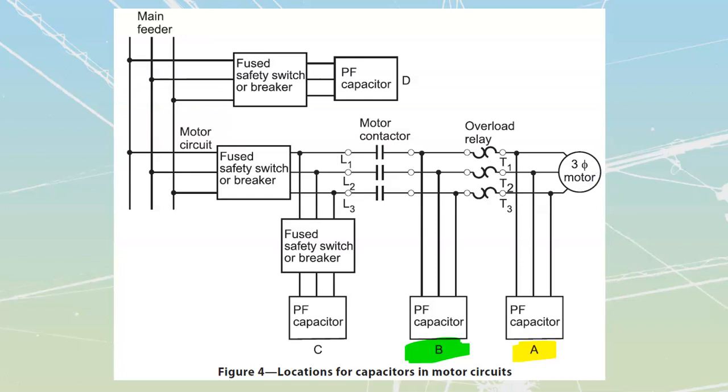what you can do is contact these companies, and they will send you a really fancy ammeter that's going to go around all three of your main lines. It's also going to have some voltage probes going to all the different lines. It's what we call a power logger. You're going to place this thing on, and leave it running for like a week.